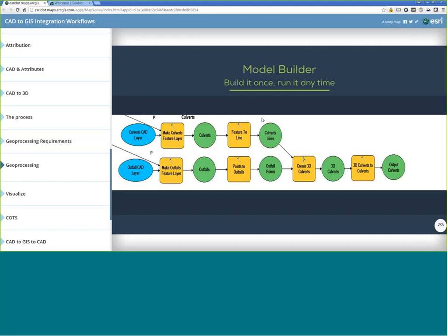And I'm going to make this geoprocessing set of tools publicly available. But just keep in mind, just because you download these tools and plug them in, it doesn't mean they're going to automatically work with your data, especially if your naming conventions are different. That CAD submission standard is the key. So you would have to go into the model and rework all the queries to match your submission standards. That is the one downside. It's unfortunately not an easy button that I can just press and all this data just spits out nice into a nice file geodatabase. There's going to be a little bit of work to make it work on your end.